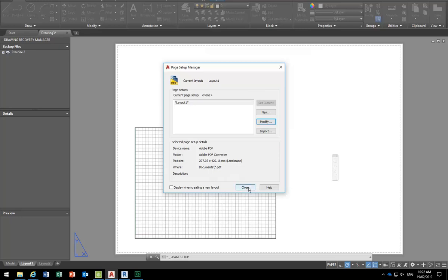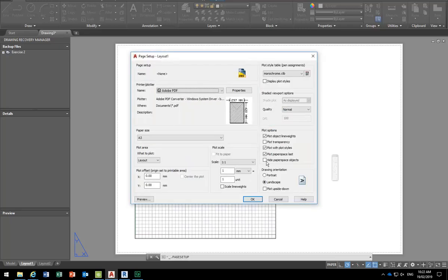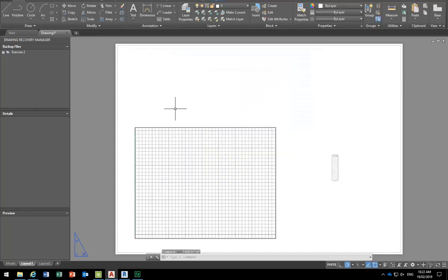What about the scale line weight? Check that line. I always forget that because you just leave that on the default. Oh yes, don't tick that. Do not tick that. No, absolutely not, just leave that one alone. It's annoying that they put that option in, because you should never need to use that with architectural drawings. You don't want to scale line weights at all. So that's really important.